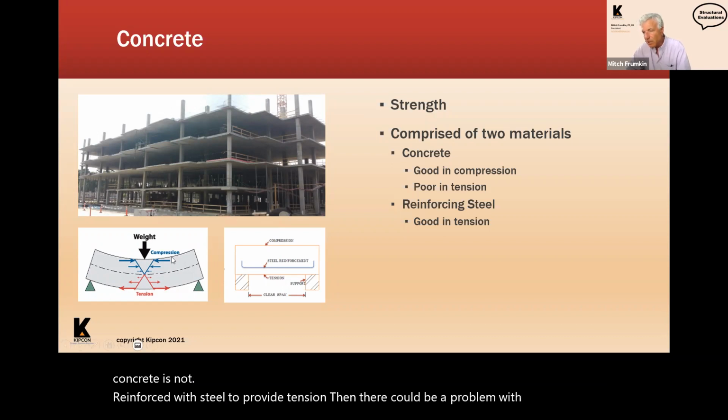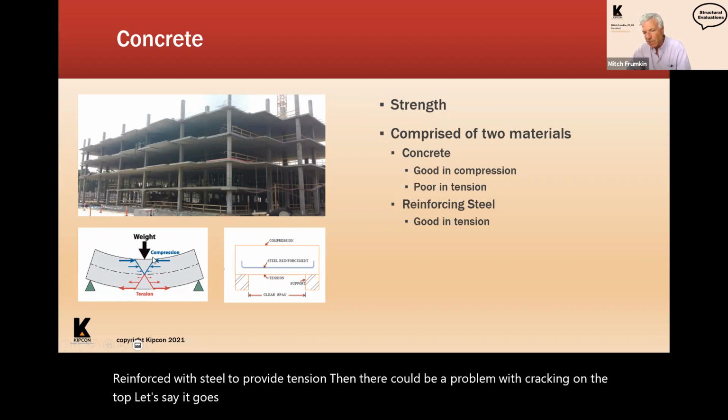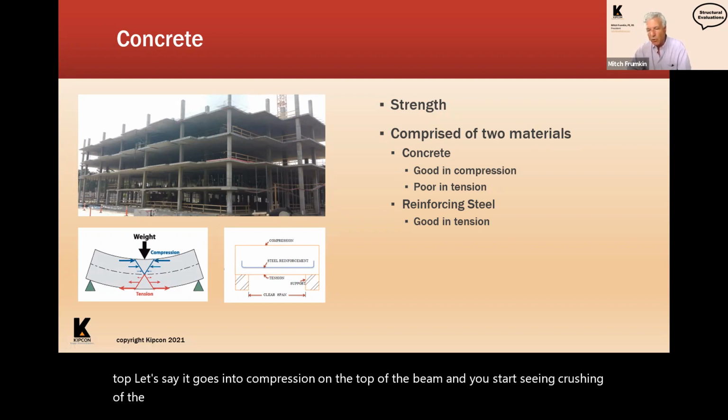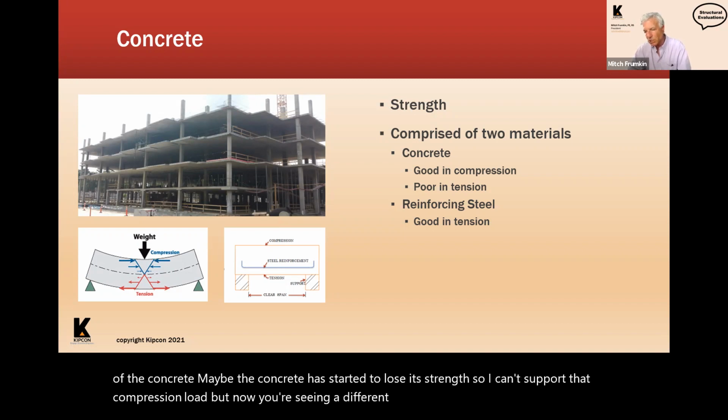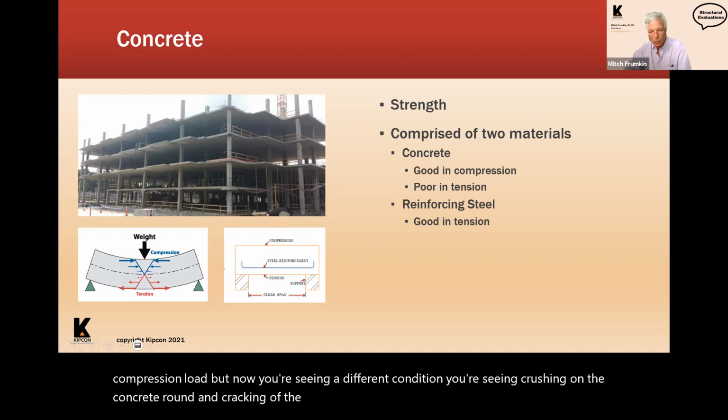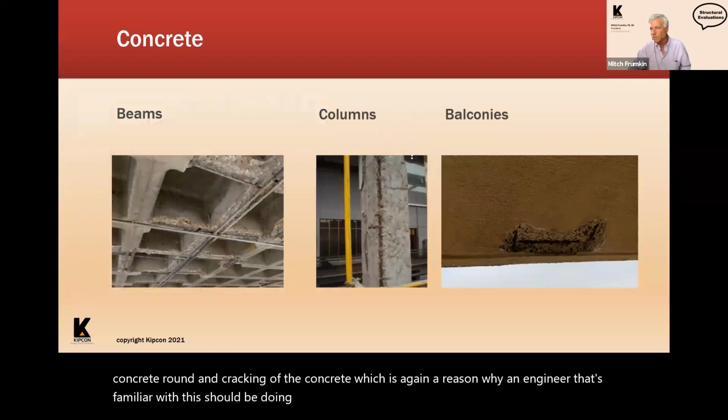On the top, let's say it goes into compression on the top of the beam, and you start seeing crushing of the concrete. Maybe the concrete has started to lose its strength, so it can't support that compression load. But now you're seeing a different condition. You're seeing crushing of the concrete rather than cracking of the concrete, which is, again, a reason why an engineer that's familiar with this should be doing the inspecting and the evaluation.